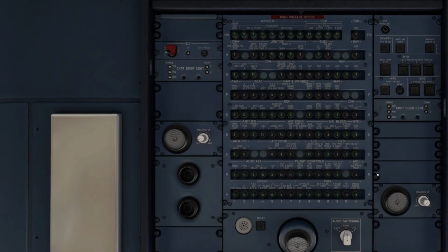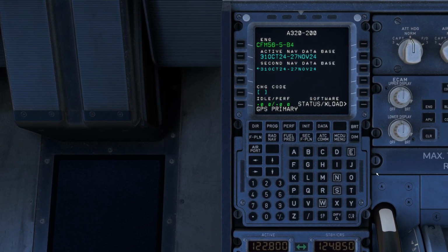So we take a little bit of a closer look into the FMGC. This will be one of the first pages you'll see. Obviously it's got the aircraft type at the top, the engines on the aircraft. We've got the CFM56 engines today. Active database, and it's got a secondary database as well. Active one is the one that's currently in use. Once we get to the end date here, we can flip over and use the secondary database, and that will activate and just show any changes that might have been made.